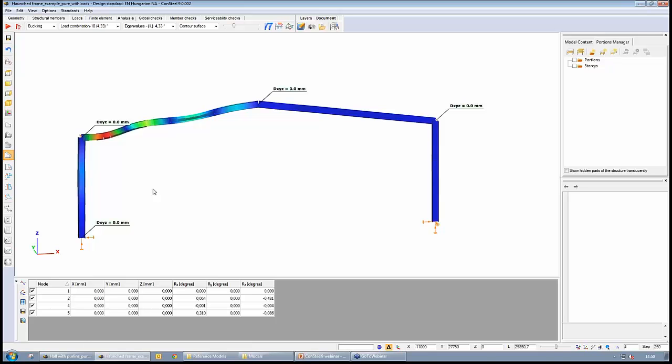And if we have an accurate model in which all the member supports are at their exact position with the exact connectivities, then this buckling calculation can be very accurate. And if we evaluate our structure model based on these buckling forms, then our results will consider all types of possible failures, which is a very safe method for evaluating the buckling performance of our structure model.